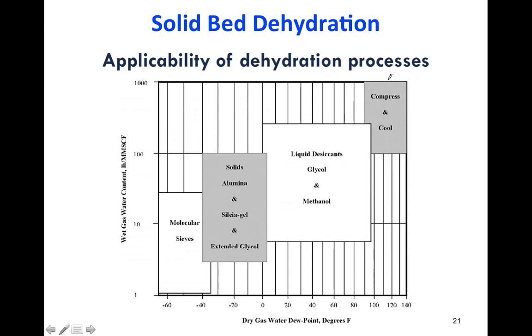So I can compress and cool my gas and separate the water. So this figure is a very nice and important figure. Try to understand it, because it shows which process is more preferred, depending on the amount of water in the gas and the dew point of the gas.